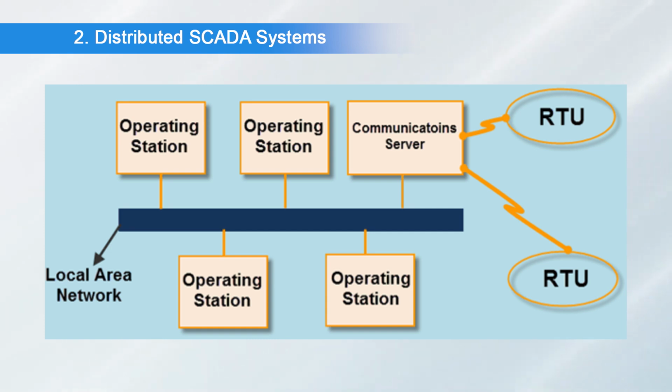So, now in this second architecture the data sharing between them is possible. Either they can be client systems or some other server systems. With this architecture, redundancy is also possible. Only a single LAN network is available, and in that you can integrate your system easily. The distribution of the individual functions of the SCADA system across multiple systems provided more processing power for the system as a whole than would have been available in a single processor system.